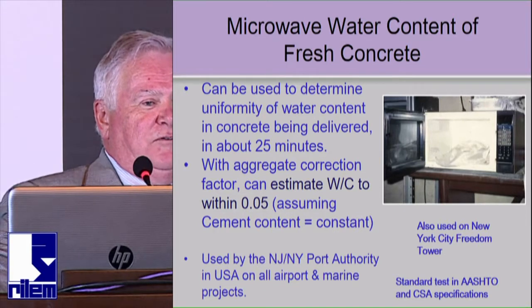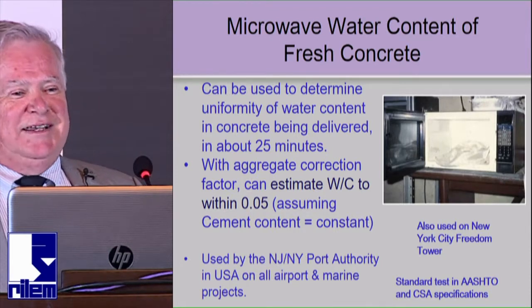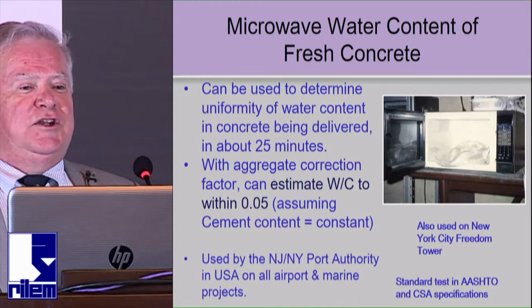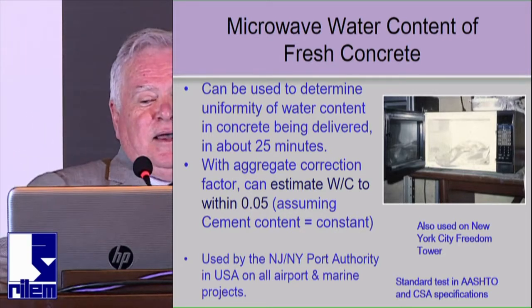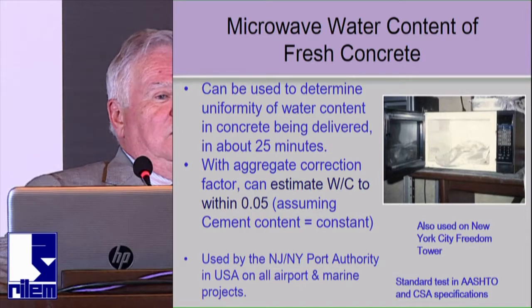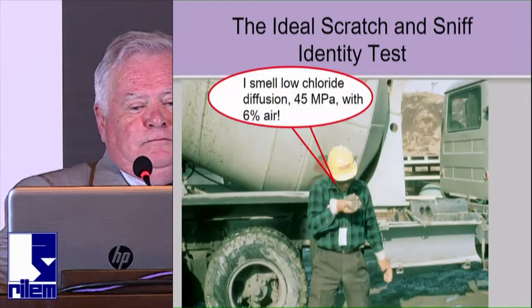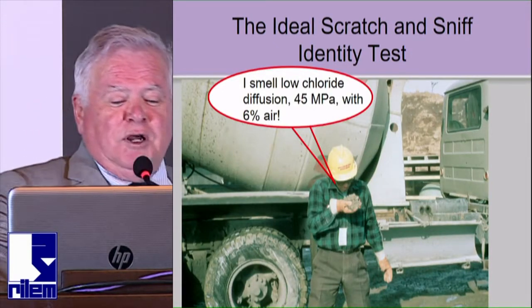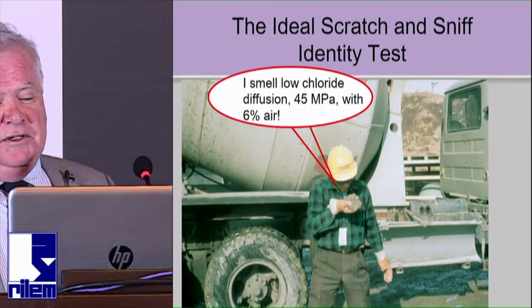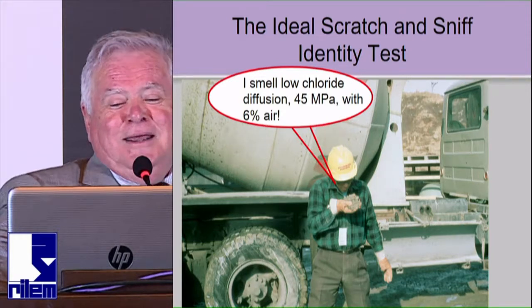I was out at the Freedom Tower site, and they had microwave ovens, and each truck had to wait until they got the microwave water content, in addition to all the other testing, before that concrete got pumped up into the structure, because they wanted uniform quality concrete that would meet their requirements. Of course, we'd like an instant test. 20 minutes is a long time, and if you wear a plaid shirt and have a helmet and you can sniff the concrete, this is what we would like, but maybe not soon.